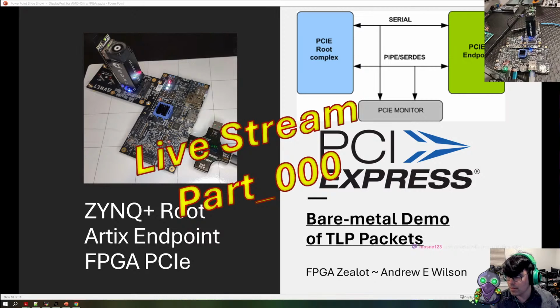Okay. Yeah, so PCIe at the SerDes level is differential, but you're not going to see it, as that part of the physical layer is all handled for you in these systems. One day it'd be cool to write a PCIe device from scratch with the reference clock and the raw SerDes lanes, and to explore how you do it at that level. We won't be looking at that part today. We're going to be mostly looking at the TLP packet protocol level.